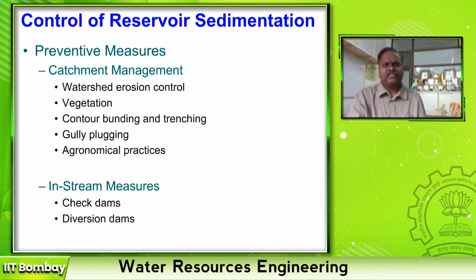Some of the methods are catchment development, thereby reducing the sediment inflow by constructing check dams, gully dams, contour bunding, trenching, agronomical measures, forestation, right, vegetation growth.